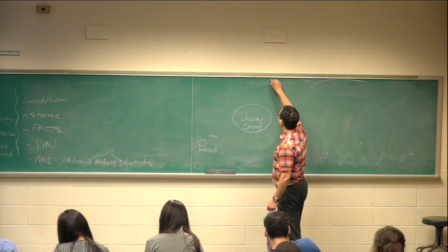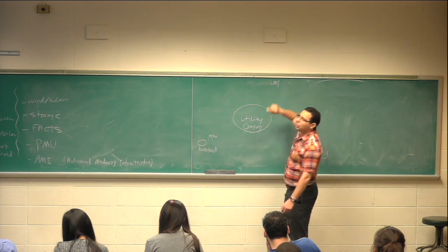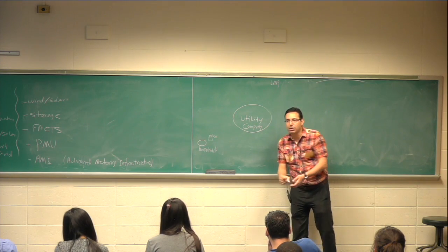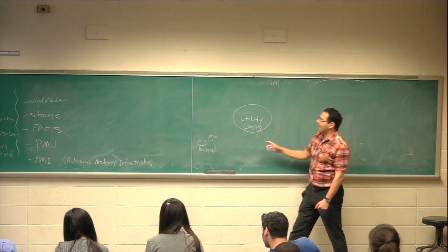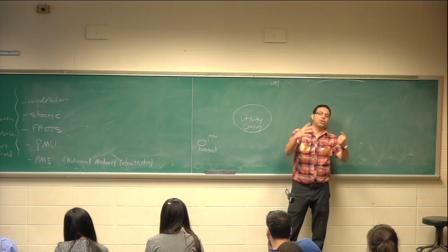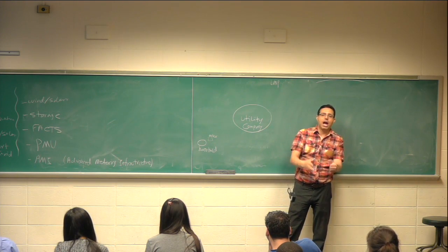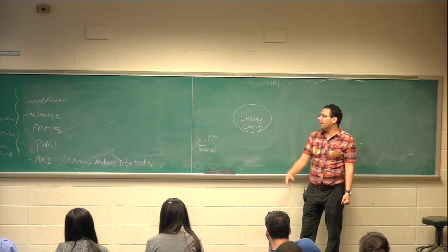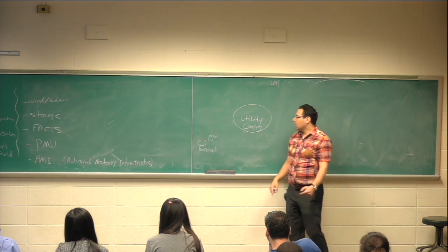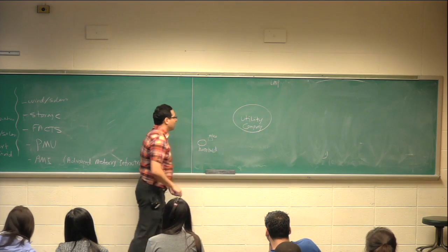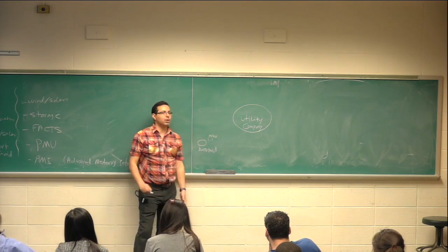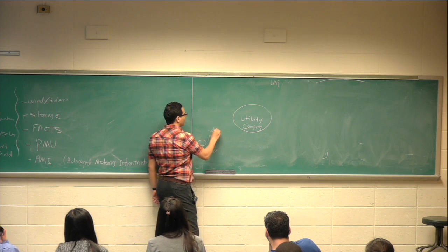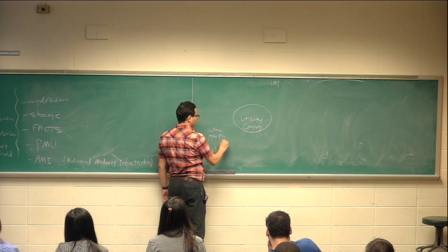But we talk about LMP, if you remember, locational marginal price. Price changes based on a location, price changes based on a time. Then you cannot say that I get an aggregation of power that I've used over a period of months. I need the breakdown. I need to know how much power I've used now, how much power I'm going to use tomorrow, or 2 hours after that, and the price is different. So the main idea for the new type of meter is that instead of measuring something, for example, every 2 hours, measure it in real time, 50 times per second.